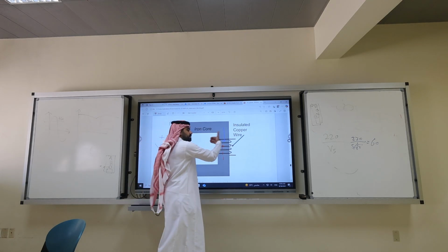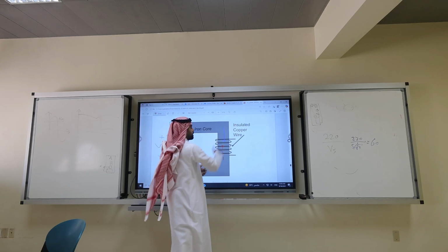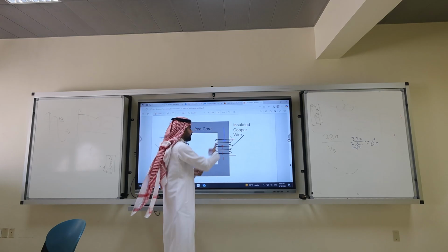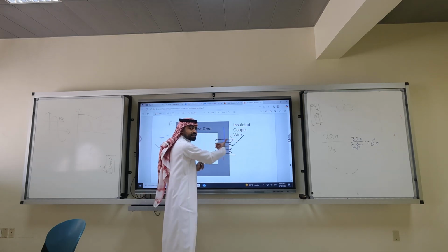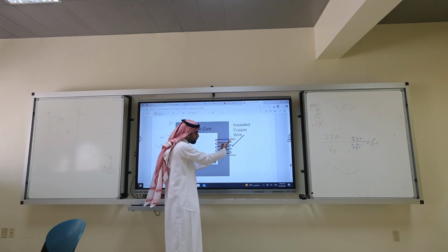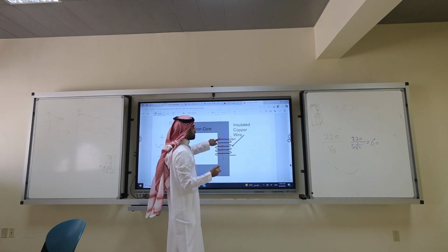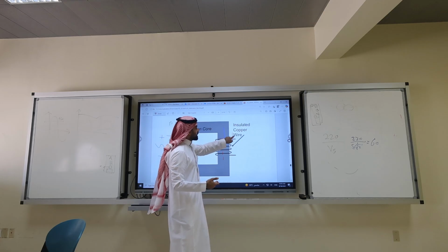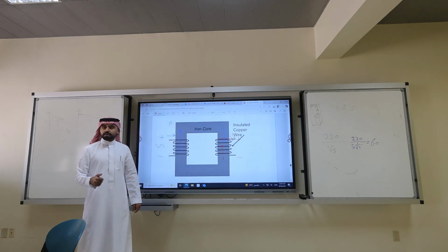Such that its current, no, the current should now be what? Leaving. Why leaving? Because we look at the winding with the right-hand rule: the fingers point in the direction of the outer turns. Get it? The fingers follow the direction of the outer turns. The right-hand rule is applied on the front turns, not the back ones. What is the direction of the current? This way. This is I secondary. So you put your plus and minus. Get it now?